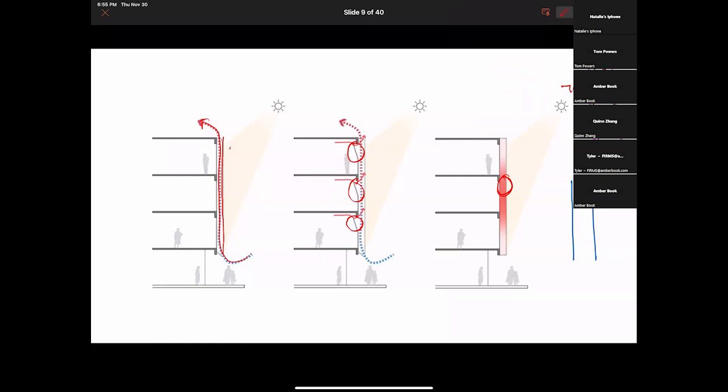And so you have a loop. The reason we care about convective loops is they can actually speed the transfer of heat, in this case from inside to outside. So it can make your building colder than it would have been even if you didn't have a loop. It's like a breeze. Not so much that you could stick your head in the wall cavity and your scarf would be blowing straight upward, as if you were in a convertible. It's not that much wind, but there's a steady breeze.